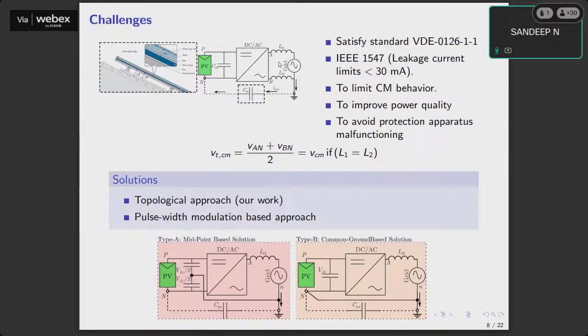But the common mode current is not going to do that. It is going to originate from one of the ports, and it will go to ground, and it will take another path, right? It is not going to flow in the opposite direction. So you'll have a current that goes from A to ground, then you'll have a current that goes from B to ground. So if you put an inductor in only one of the legs, then we will be able to attenuate the common mode current only in this path, whereas in this path, there is no attenuation.